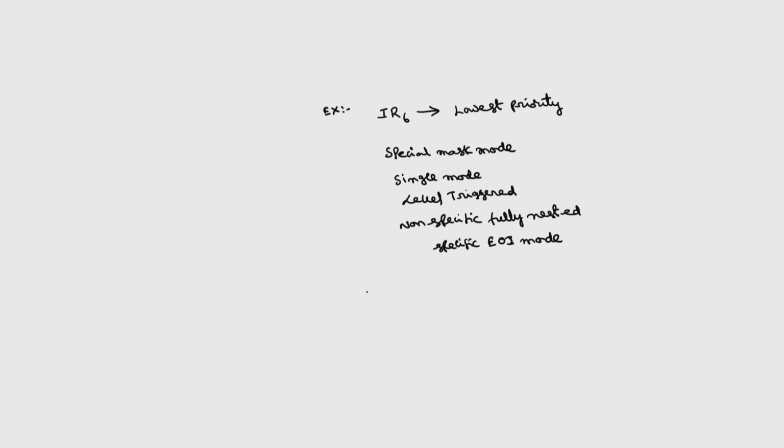So what are these? ICW1, ICW2, ICW3, ICW4, similarly OCW1, OCW2, OCW3. There are totally 7 command words: 4 initialization command words and 3 operational command words. Okay. So if I go for this operational command word 1,